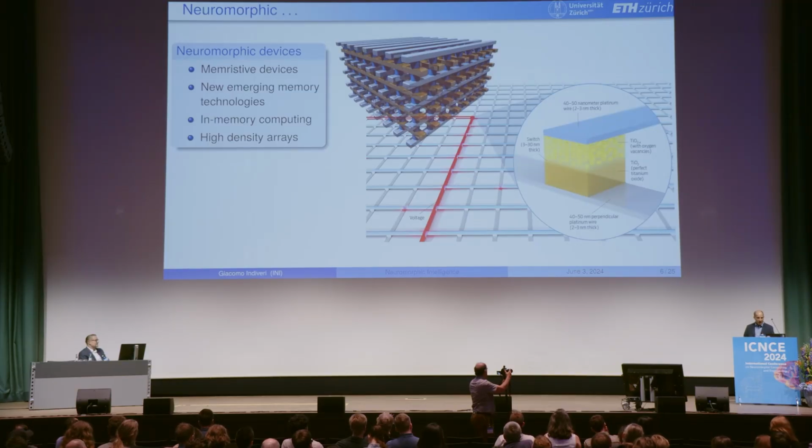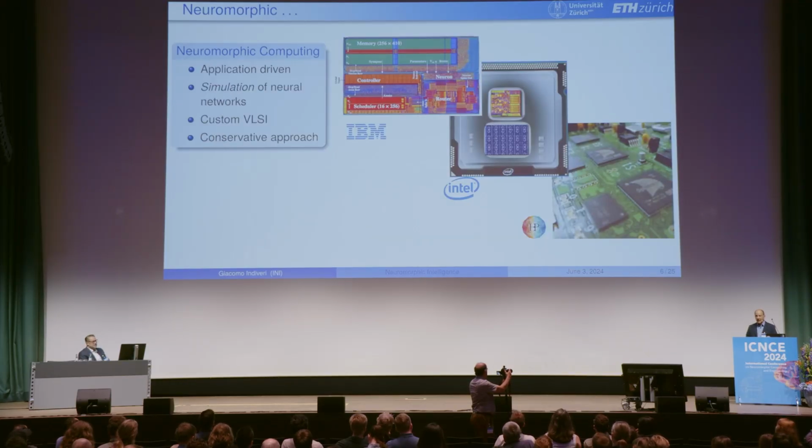Then in 2014, thanks to the DARPA Synapse project, IBM produced an impressive chip with 1 million neurons using digital circuits, so not really emulating the properties of real cells with the physics of transistors, but using at least asynchronous circuits. Some of us in the room were actually involved in the DARPA project and in IBM TrueNorth. This was really, as I said, an impressive achievement, but it was a simulation engine, or if you want, an accelerator for spiking neural networks.